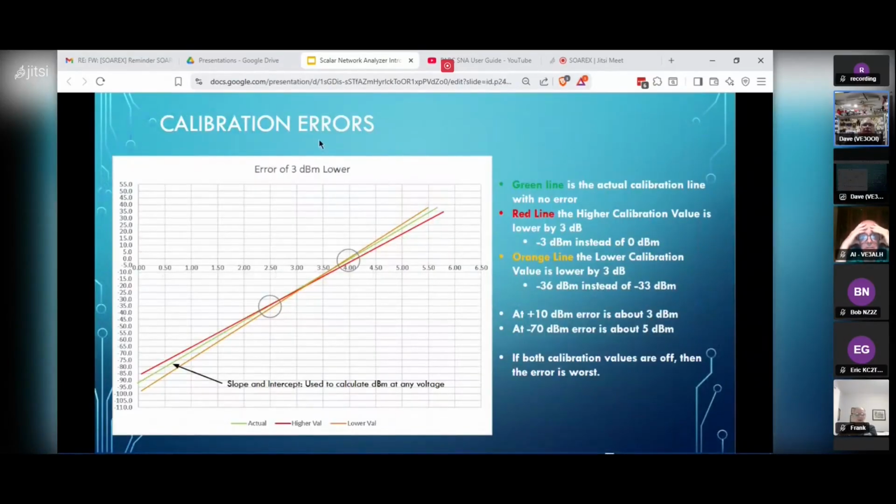The next gotcha is calibration of the 8307. Because we're using a 2-point calibration, we could get some errors in the slope and intercept. Here I'm showing 3 different calibrations where the 2 calibration points we used differed slightly.